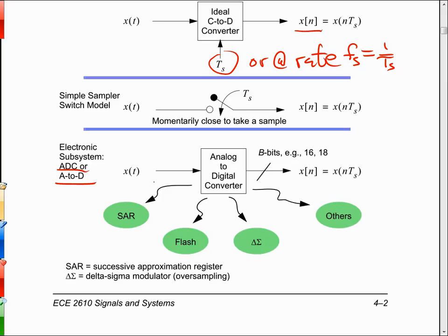This one is a bigger board that has more memory and a daughter card, and it has a nice audio band, A to D and D to A in stereo, so it's got the stereo jacks on it, which you can clearly see are line in, line out, headphone out, and microphone in. This is a TI C6713 DSP microprocessor,